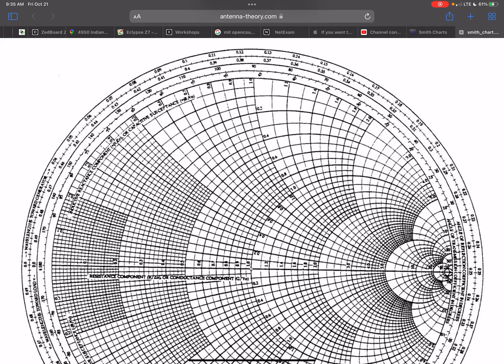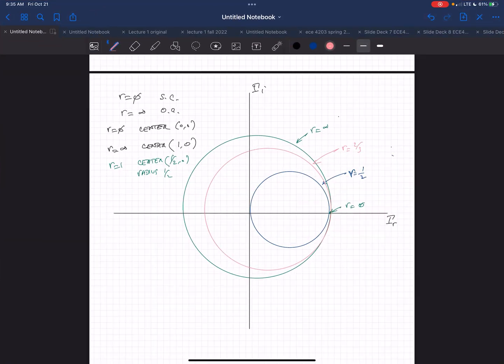Also, just remember that this is the normalized impedance, meaning that I've divided the impedance of the load by the characteristic impedance. It's normalized, so the maximum amplitude of impedance in this case is basically normalized to that value. So, okay. That's R, as the real part of impedance is changing.